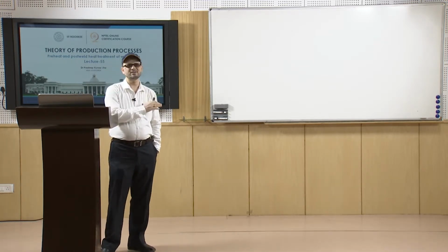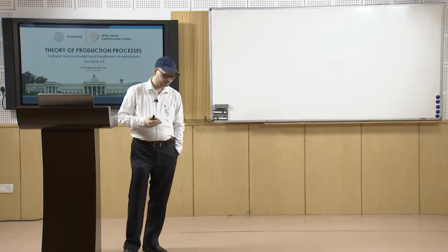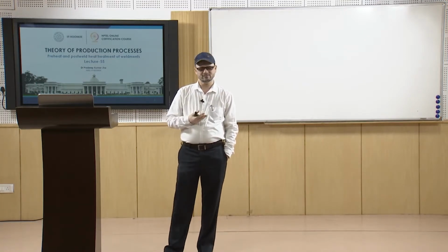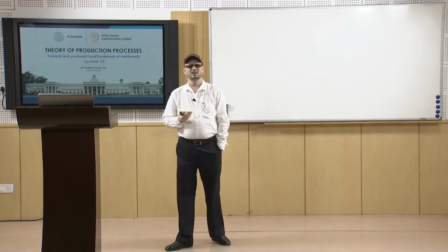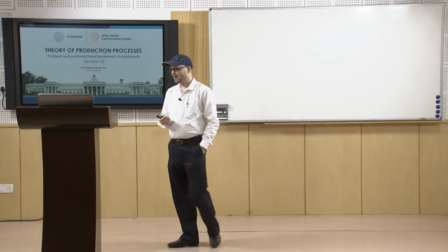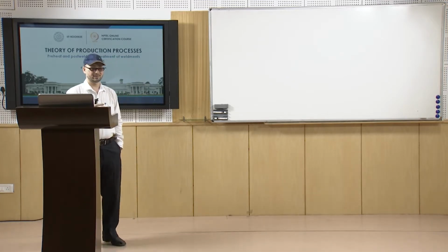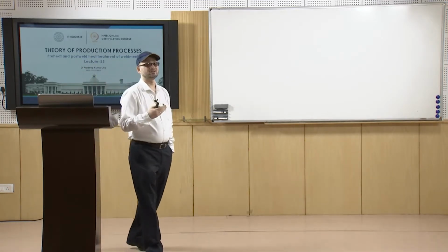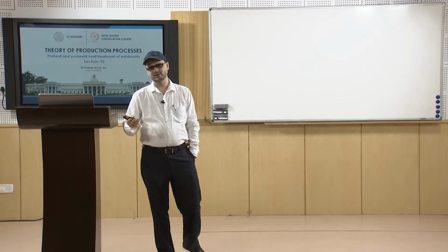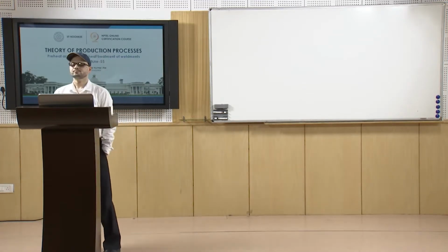Hardenability increases with the carbon content. If the carbon content becomes larger, you have more chance of formation of martensitic phases, and in those cases there will be chances of more stresses. As the carbon content increases, or even the alloying elements increase, that also has an effect on hardenability, which we will see, and in those cases you need the preheating.